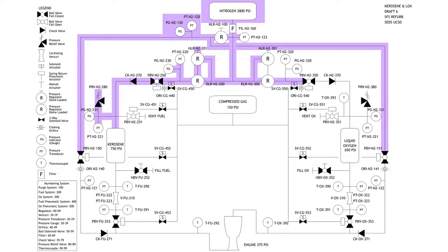John, you have a pressure transducer right after the regulator and then just above the tank. Yes. That's just to account for the pressure loss in that pipe? Yes, it's pretty redundant. Yeah, but mechanical redundancy is better than playing games and risks. What happens is that you basically create a pressure boot on top of your kerosene tank. All that purple that you see on top of my kerosene tank, that's what happens over time: eventually it goes from 5 psi all the way up until that 750. So I keep regging that up, and I get to 750 eventually.